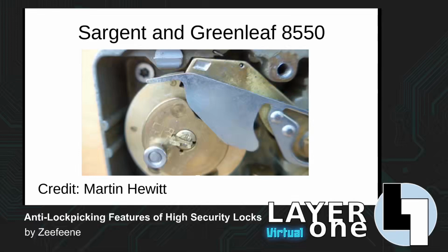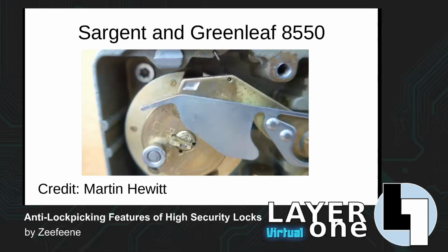And if it's in the wrong position, well, then it will bring the lever nose down. The lever nose will test for a moment of a second, but then it will effectively bounce off the wheel pack. And so you only have that momentary fraction of a second to get any information out of the lock before the lever is once again raised off the wheels. If you've aligned everything correctly, then it fires fully all the way into the slots in the wheels, and you can then retract and open the lock.